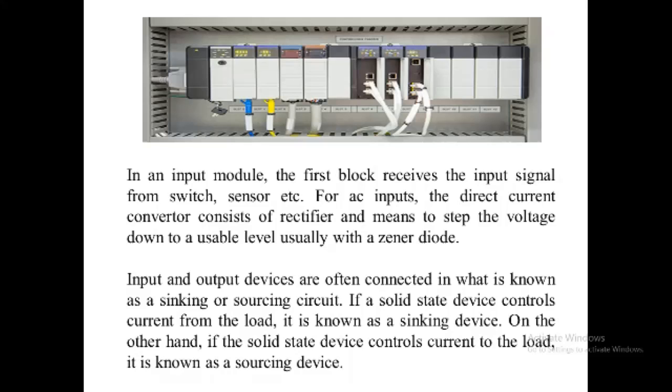Hence, these input and output devices are often connected in what is known as a sinking or sourcing circuit. If a solid state device controls the circuit from the load, then it is known as sinking of the devices. On the other hand, if a solid state device controls the current to the load, it is known as sourcing of the devices.